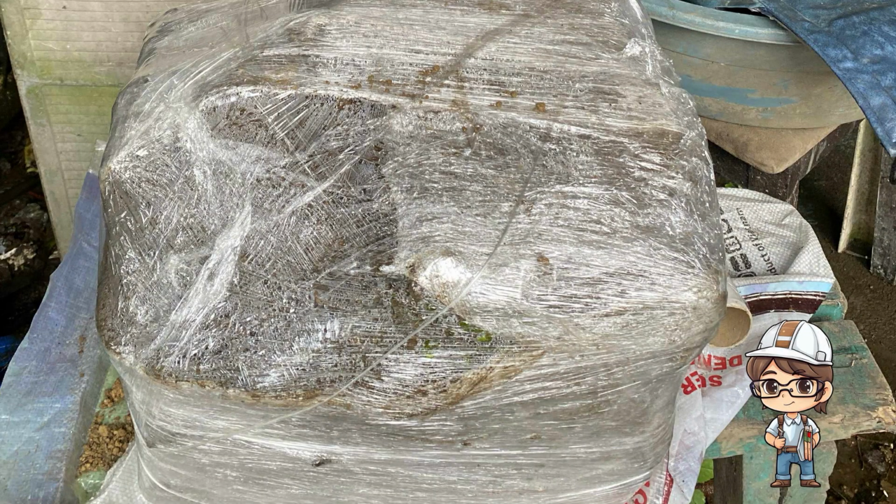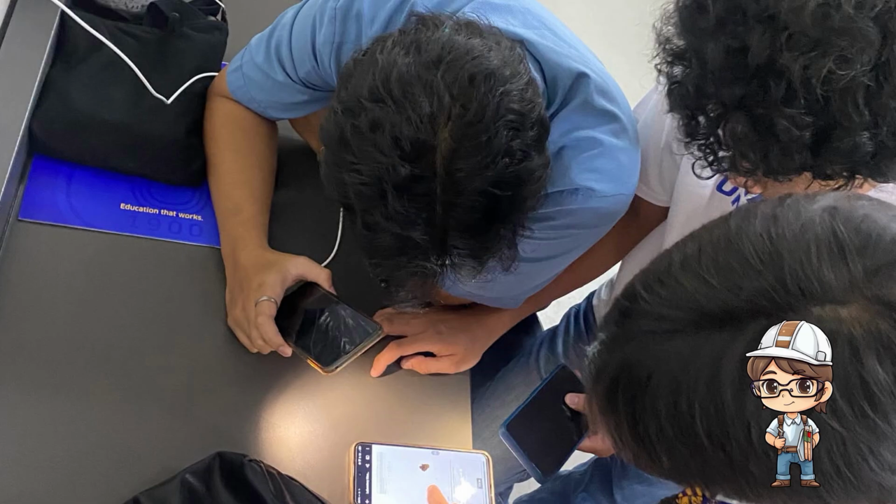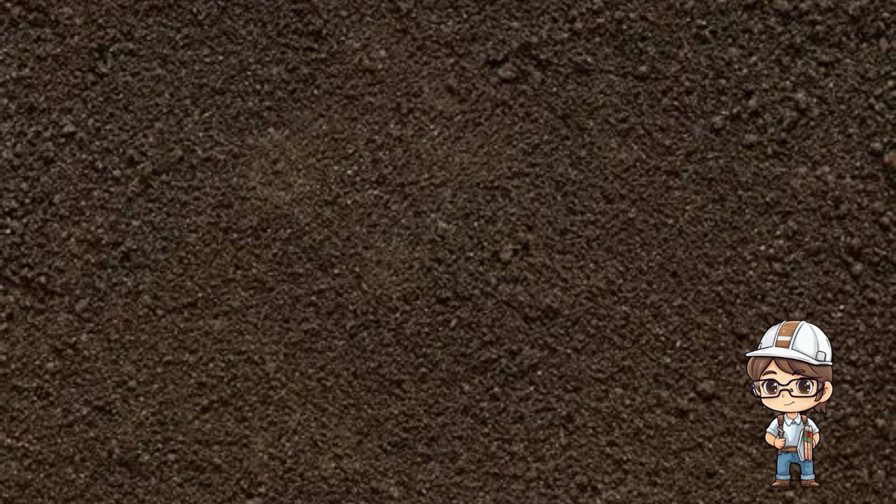After collecting soil samples, we take them to the laboratory for experimenting. First, visual classification of soils. This test involves a qualitative assessment of soil properties through direct observations. The students describe soil texture, color, structure, particle size, and angularity. This test develops an understanding of soil identification and classification based on visual and tactile observation.